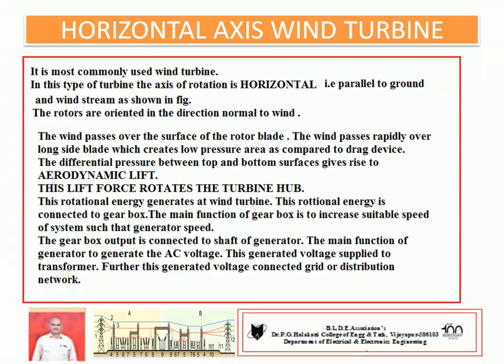When the wind passes over the surface of the rotor blade, it will create a low pressure area as compared to a drag device. The difference of pressure along the rotor blade creates aerodynamic lift, an aerodynamic effect. Hence, it starts rotating.